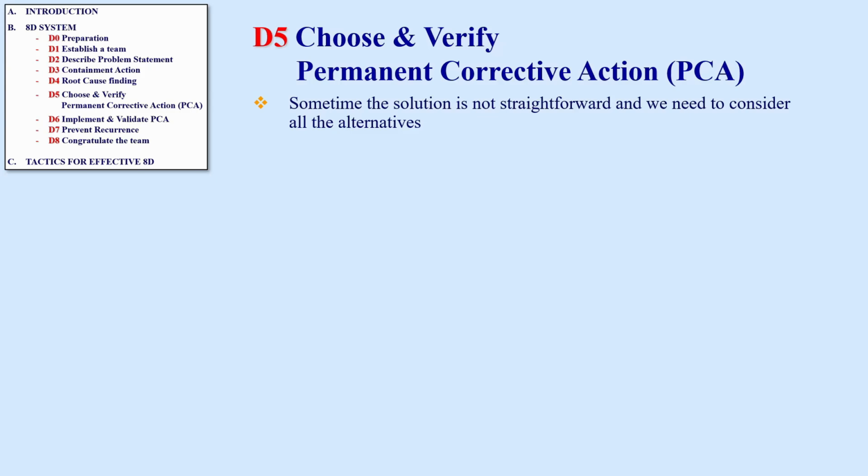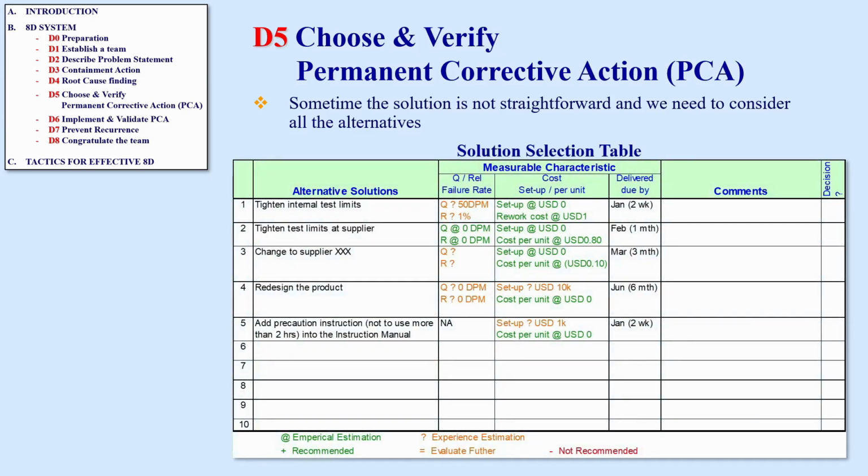Let's say we have a customer-reported functionality issue. Your failure analysis team has concluded that it was due to a design marginality issue. When the value of a specific capacitor is at the marginal spec limit, though it is still within the limits, the product might experience an intermittent issue after being operated longer than 2 hours. In other words, this is a design issue.